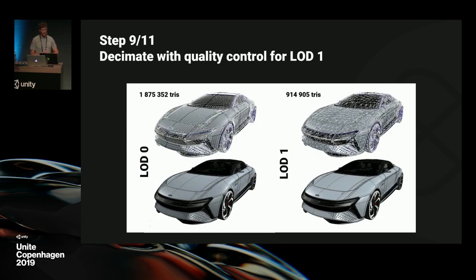For LOD number 1, we will use the mesh decimation function. And decimation in Pixies can be driven by either a polygon target or by quality control criteria. These criteria can preserve the original shape, UVs, and normals, which can be very important for CAD models. We don't want things to look like a potato in the end. So for this LOD, we use the decimation with quality control. And we approximately cut the number of polygons by half here, without losing shape precision from a very reasonable distance. Decimation is also a very, very important algorithm, and Cédric will tell you more about it.